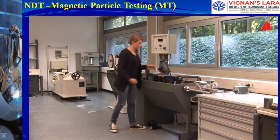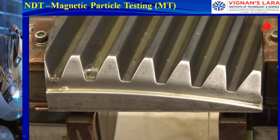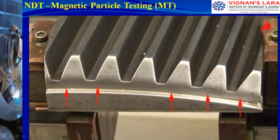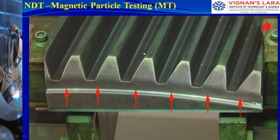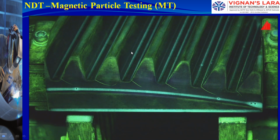Placing the gear wheel between the magnetic pole pieces, magnetizing and applying magnetic particle suspension. Already in daylight there are indications of cracks, and again they are best visible under ultraviolet light while darkening the daylight. The visible cracks are so-called fatigue cracks. They have been generated during the operation of the gear drive due to a mismatch of the gear wheels.